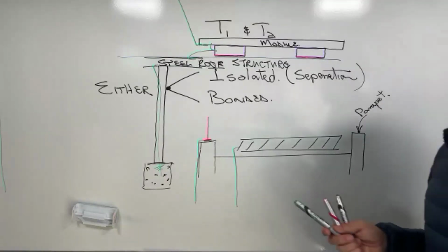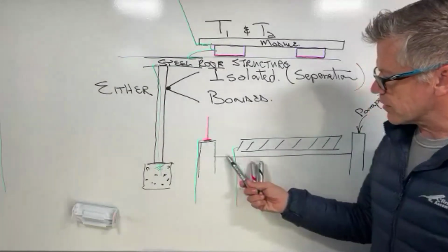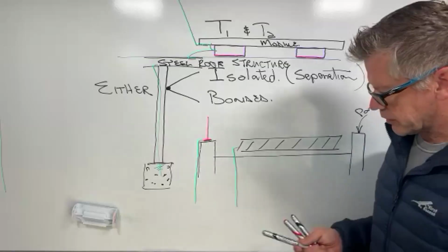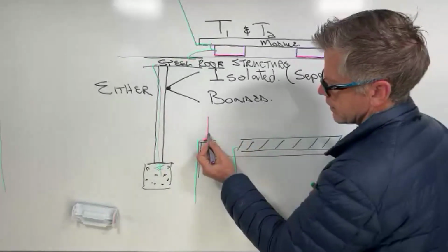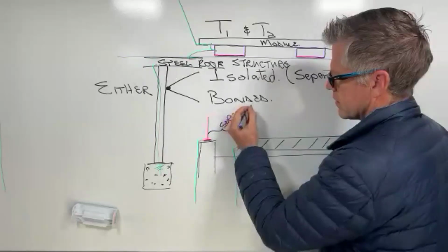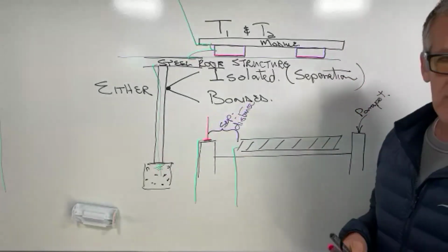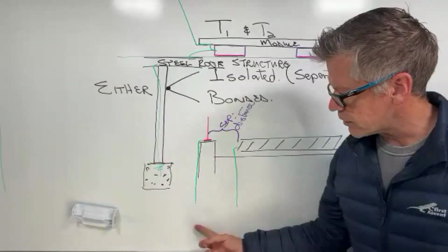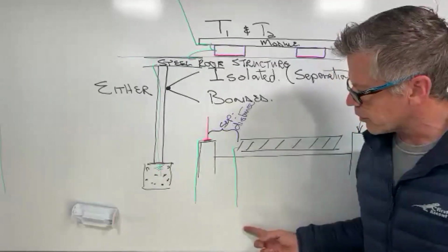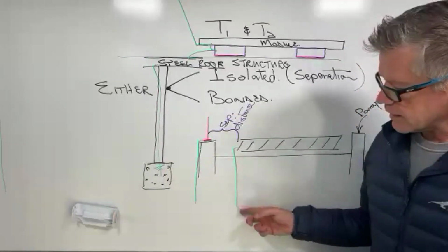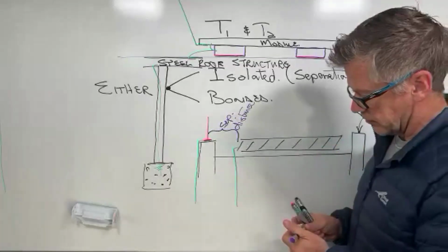So what I've just drawn while you were busy chatting is I quickly drew a flat concrete roof. I've got the air termination on the parapet. The section over there is the separation distance. The difference over here is that your lightning protection goes down to the ground over there. It's bonded to your earth bar and your DB board, and this is bonded to the earth bar and the DB board. But this section over here ends up with type 2 then, if I remember correctly.